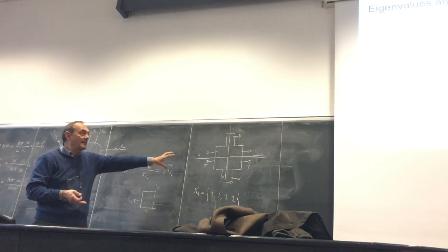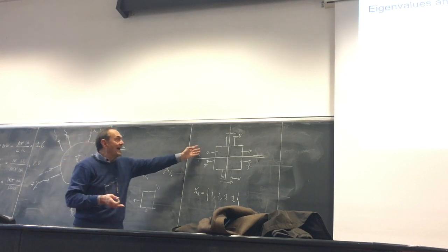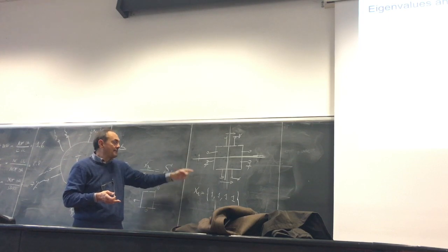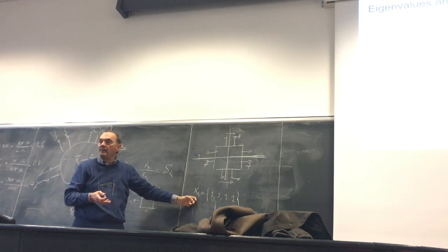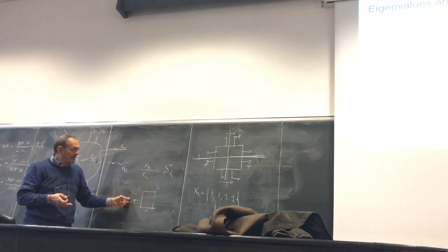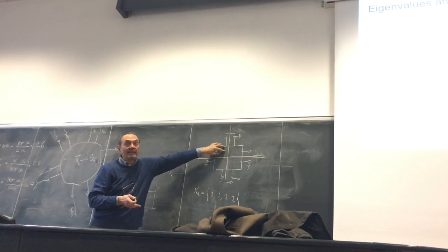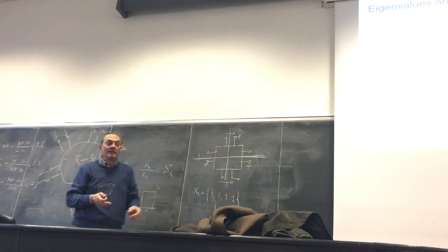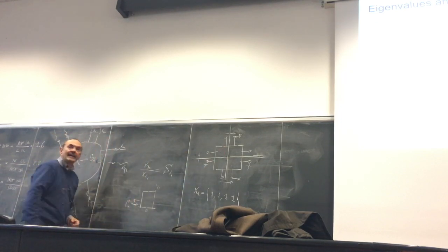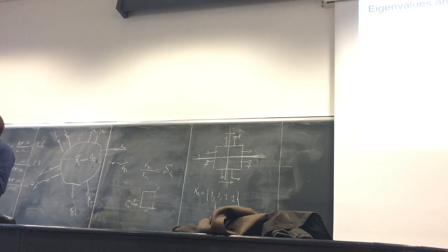In the case of the scattering matrix, if I excite my structure with incident waves which correspond to a given eigenvector, what I observe from this single part of my original structure, that is the reflection coefficient I observe here, is just the corresponding eigenvalue.